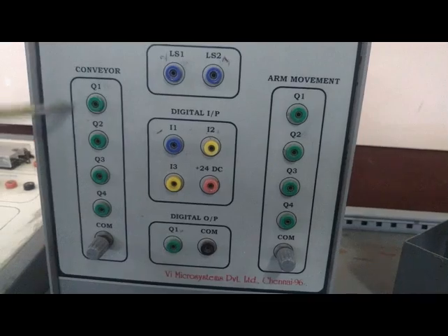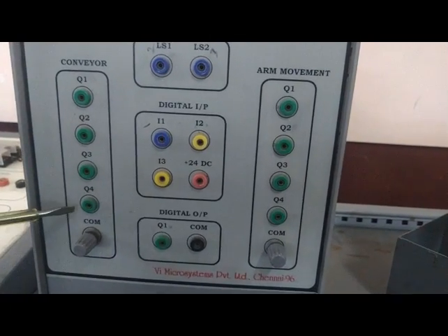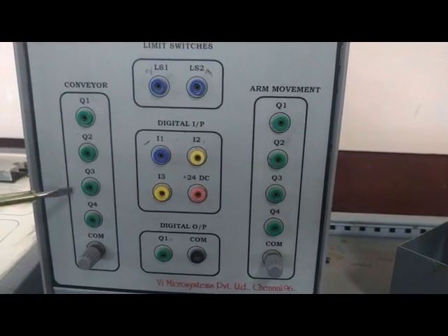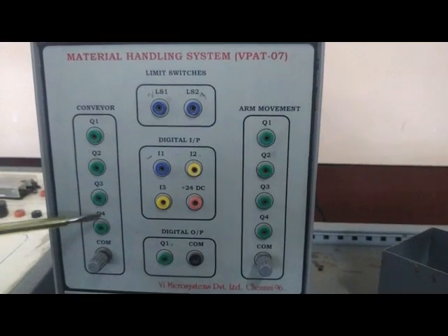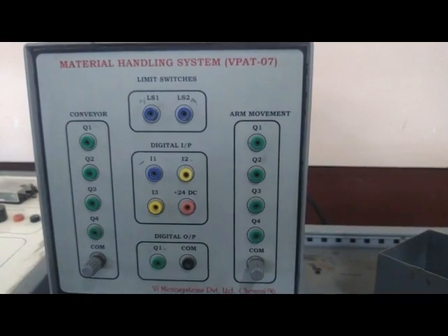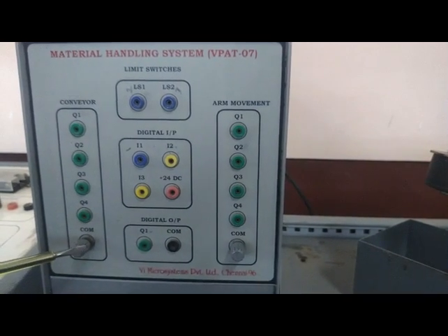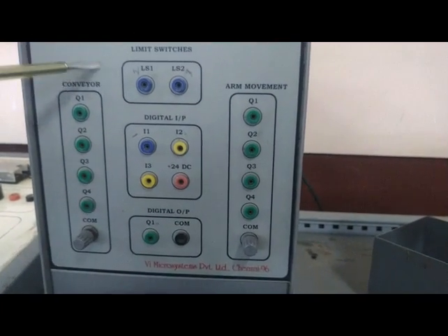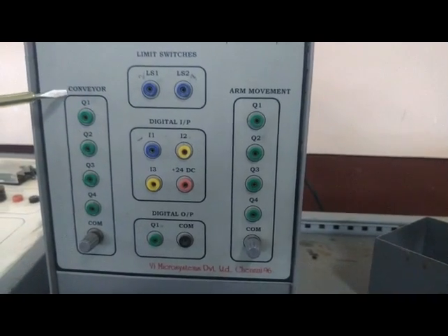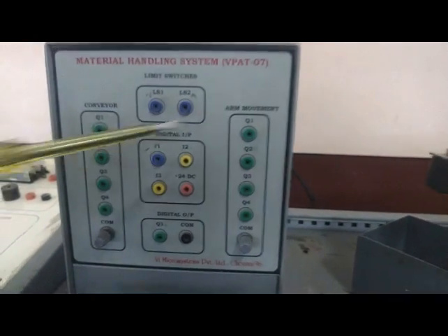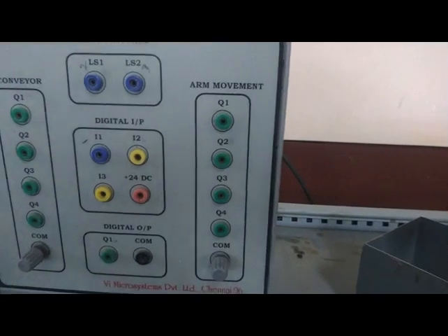Right, you can create an impulse, you can adjust your frequency. Based on your frequency, the output will go to individual coils from this particular point itself, which we are connecting through the potentiometer, where you can adjust the speed of your conveyor by controlling the speed of your stepper motor. Similarly, the same for arm movement as well.